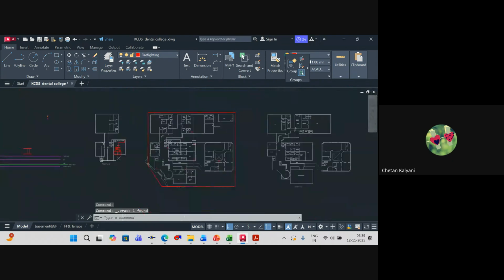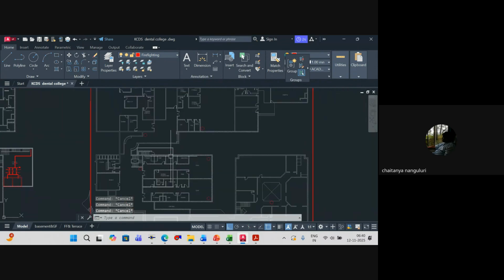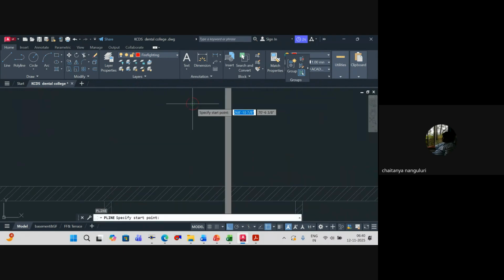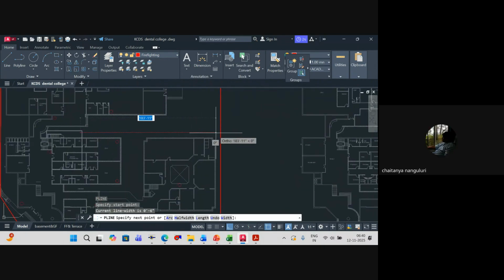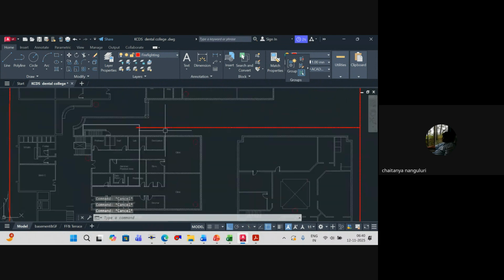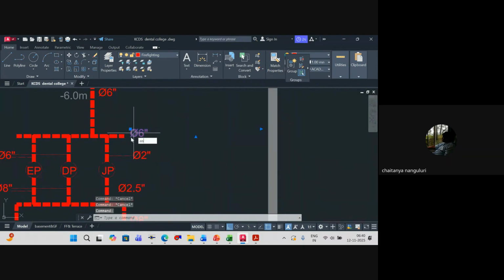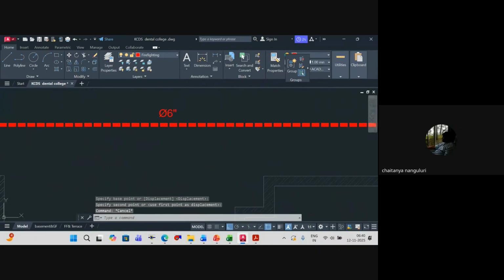Okay. So at this particular location, let's say we wanted to place our hydrant valves. First of all, I have to join this pipe to this pipe or not? This is our outlet pipe that's coming from your manifold. So from here to here, we'll take this particular pipe, which is connected to this location. So automatically, this pipe will be 150 mm. This entire thing will be taken as 150 mm.